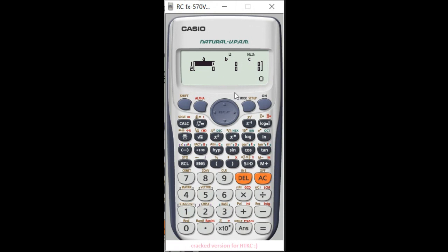So there is my matrix. Remember, for the first equation, my I1 was 6, I2 was 4, and that's 4, the EMF here. And then the other one was 4 I1 and 5 I2, equal to 2 for the EMF. Once you have that, all you have to do is press equal, and there you've got your I1, and I1 is 0.8574.